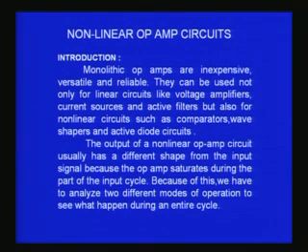One of the simplest examples, as I mentioned, is a comparator. A comparator basically compares two voltages applied at the two inputs, and the output will show which one is larger of the two or which one is the smaller of the two, whatever. Therefore the output can be a completely different shape with reference to time compared to the input. That is what I want you to realize here, because there is no linear relationship.